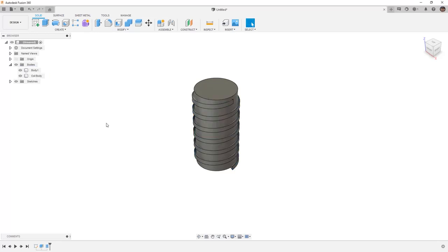From here, you might be wondering why we're even bothering to create a coil and a cylinder if we simply want to create a thread. If we flip the triangular profile around to the external side, we could simply use that as a thread, but there are some differences that we want to make sure that we are aware of. When we're creating a thread, we need to be mindful of the starting position and its relationship to the solid we're removing it from or adding it to.